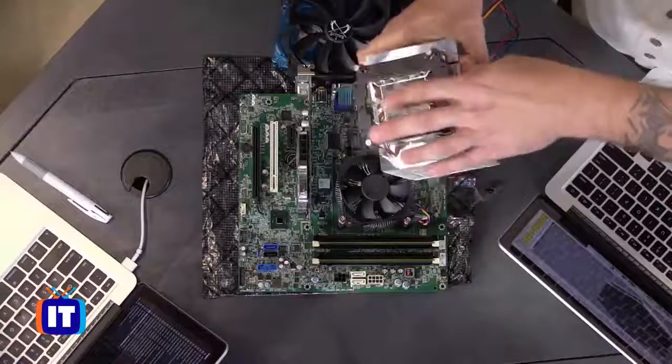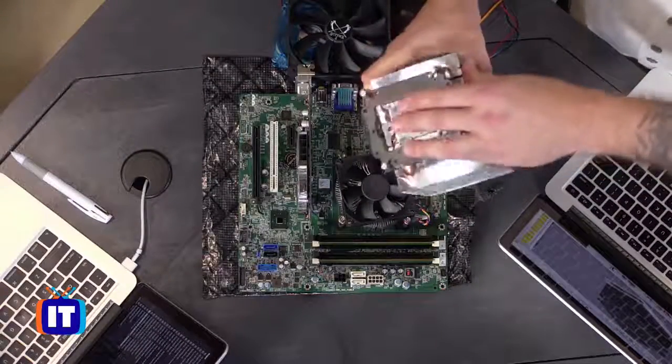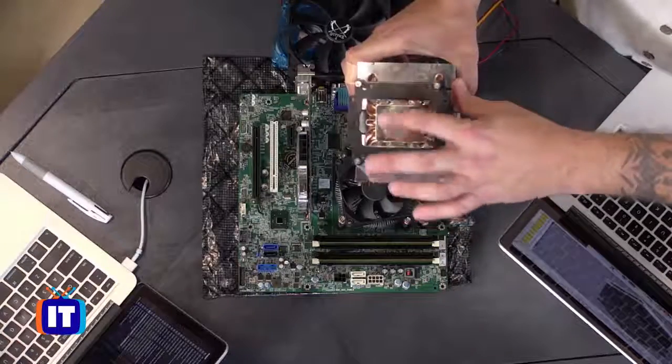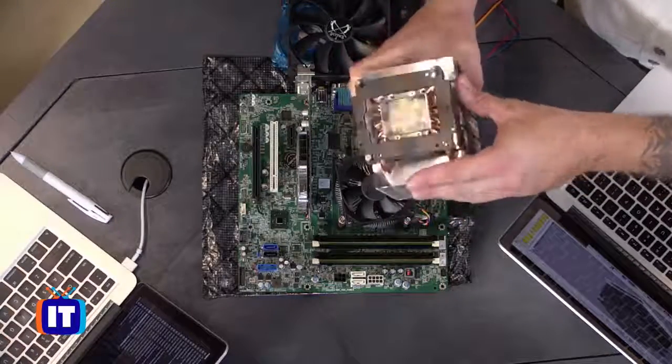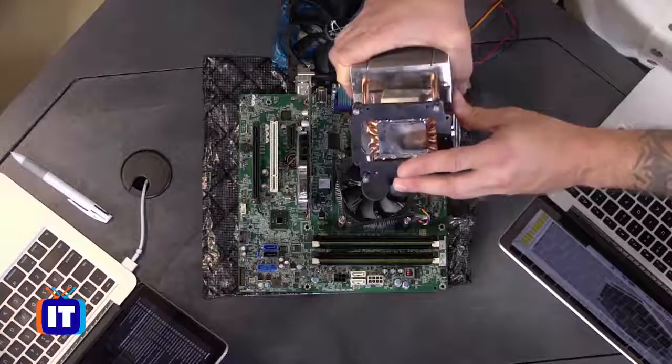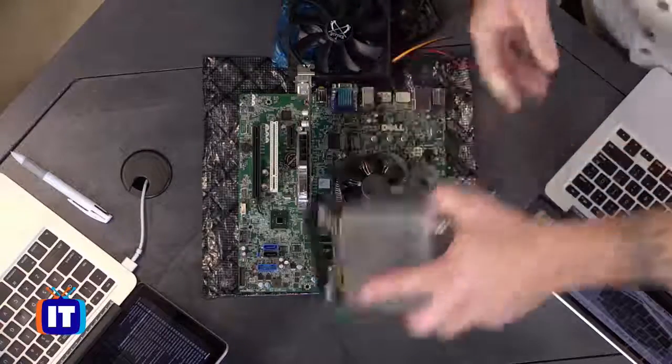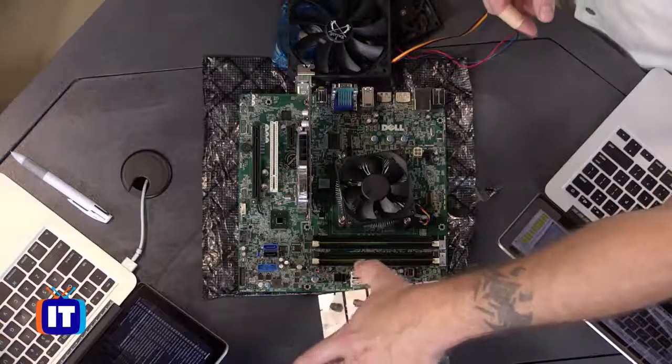All right, now I did mention that we have fans, right? And we have our heat sink. Well, here's another thing in combination with the heatsink. If we could go back to our big old massive crazy heatsink that we've got right here, notice that we have this surface, and I'm not using this. This should be cleaned off, guys. You certainly don't want this looking like it does right here with my fingerprints on it. But what we can't see, and we won't be able to see much if I keep blinding you guys there, is the fact that the bottom of that heat sink isn't as flat as we think it is, all right? It actually looks like the surface of a golf ball, or milling marks on it, scratches on it.